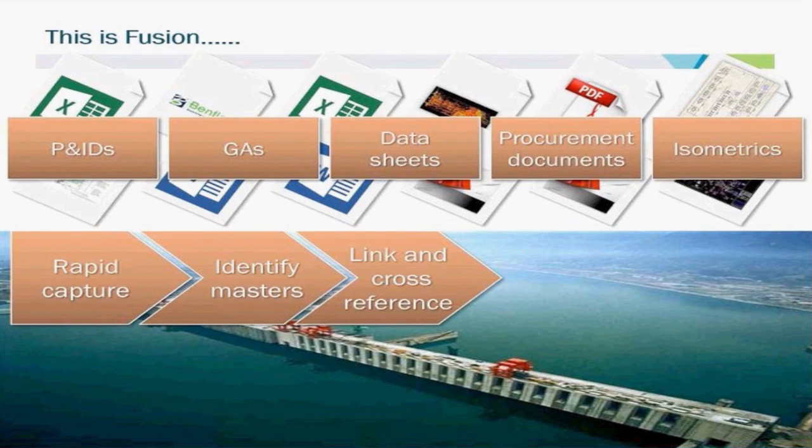Once I've gone through these 3 steps, I need to do a quality assurance and quality check on these drawings and documents, so that after the identification of the masters, I identify which one of these is closest to as built, and whether I should be redrawing them so that they are as built. And once that quality assurance process is completed, you start repurposing it.